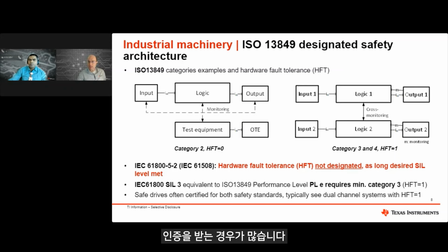The architecture 4 example does not cut power, but turns the PWM off through a fast AND gate. It requires very short periodic diagnostic test pulses to validate the STO function can still disable the output of the buffer independent of the non-safe PWM signal. The RC filter at the output of the buffer will remove these short test pulses to ensure the gate driver doesn't turn on or off during the operation, and the propagation delay of that RC filter will contribute to the overall PWM propagation delay. So this needs to be considered in the system design.